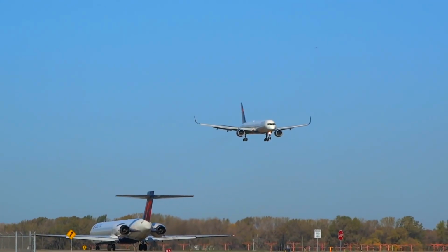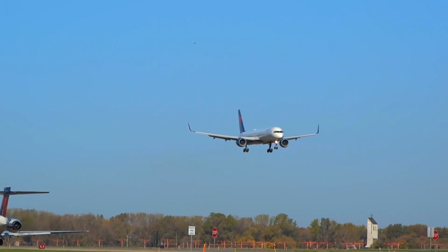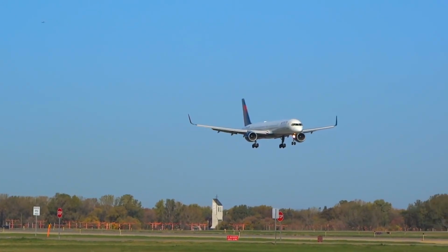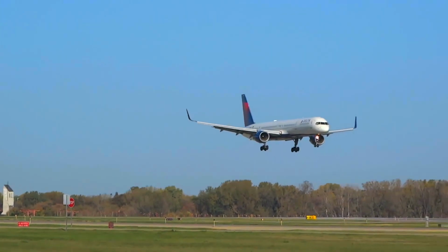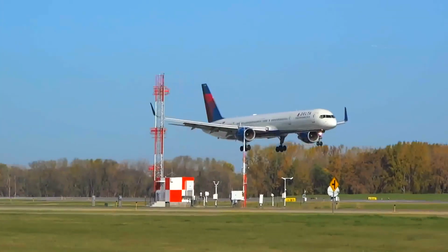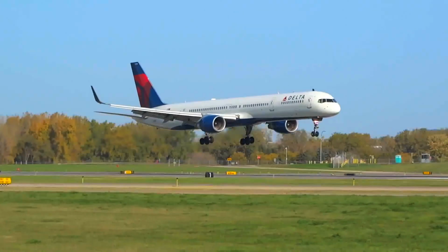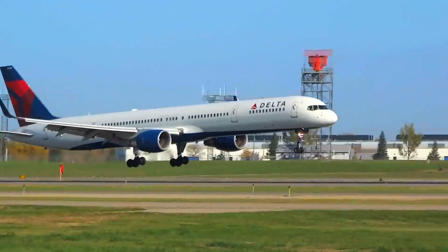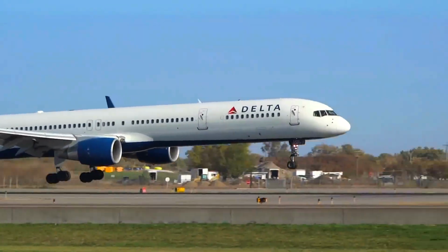So the captain announces that we have lost all engines and the aircraft goes into silent mode. We don't have the APU, we have lost hydraulic pressure, there's very minimal control of the aircraft. This, my friend, is time where the RAT system kicks in, or the RAM air turbine system.